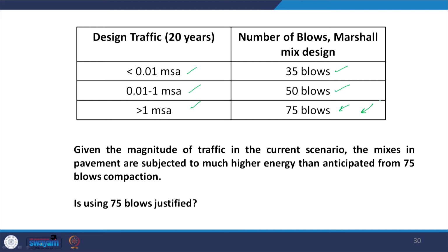And one of the differences between the Superpave gyratory compactor and the Marshall compactor is that the Superpave gyratory compactor gives much higher energy to the bituminous mixture.